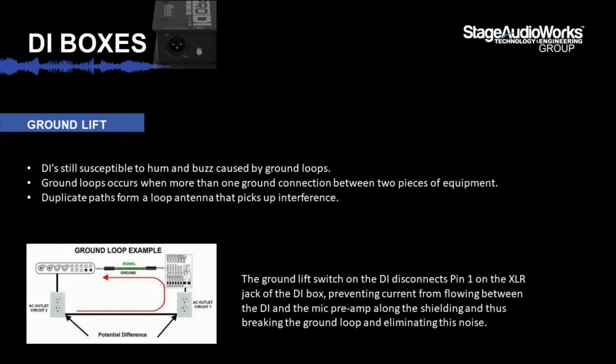A lot of the time when you hear hums or buzzes, even if you're not sure if it is a ground loop, it's worth having a stab. Often it can fix your issues if they are ground loop. If it doesn't fix it, then your hum and buzz is not generated by a ground loop.